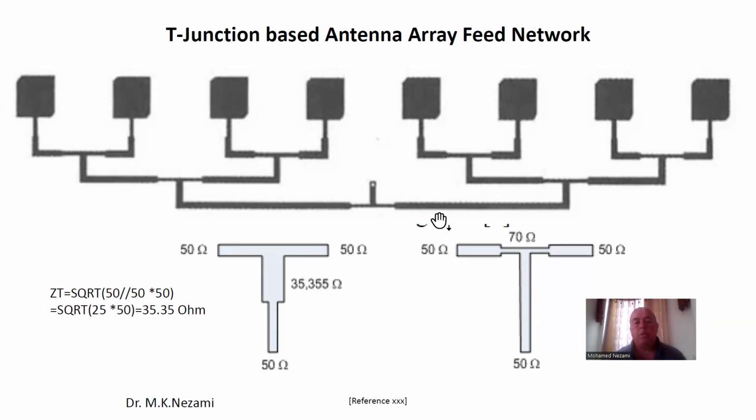Sometimes you need to extend the width and keep track of the length so you come exactly at the center-to-center distances of these elements, which are most likely going to be either a half wavelength or further, up to 0.7 of a wavelength. So the spacing in here really determines how you're going to design this.